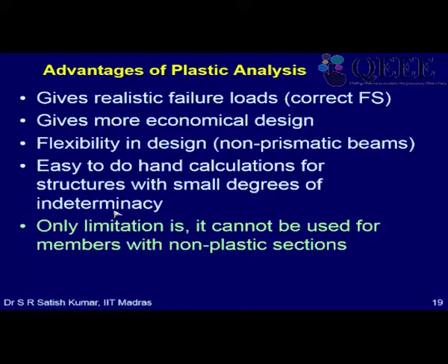Many people model these frames in some software, and they give incorrect support conditions, support constraints as they are called. So if a support is a hinge, they may release the moment but forget to release the displacement, or the other way around. Then from the solution you wouldn't know whether your solution is correct or not. So you can use this to check on your solution.